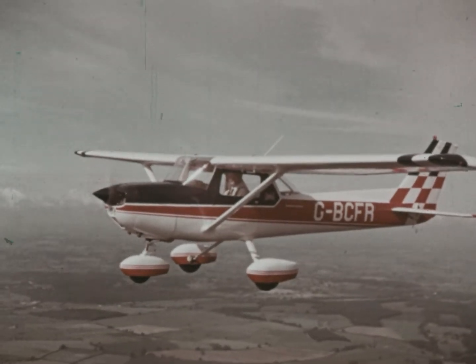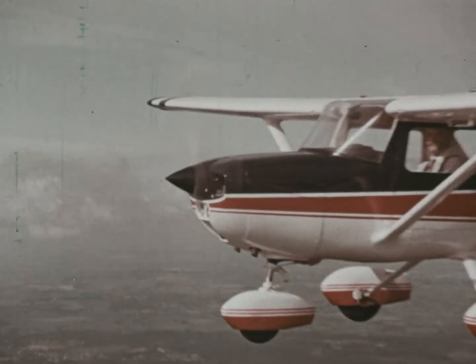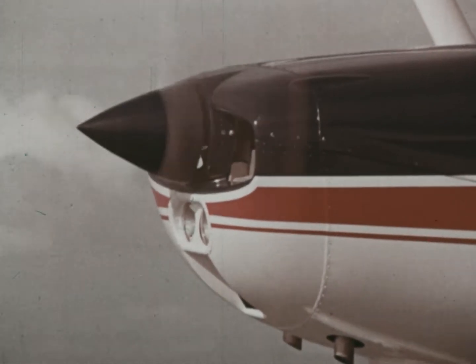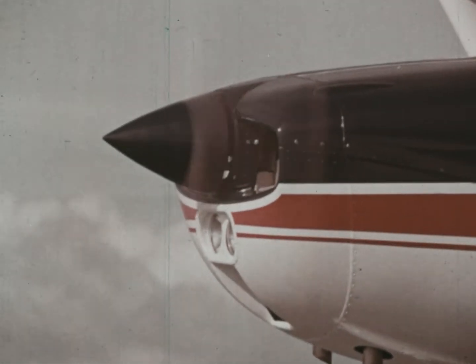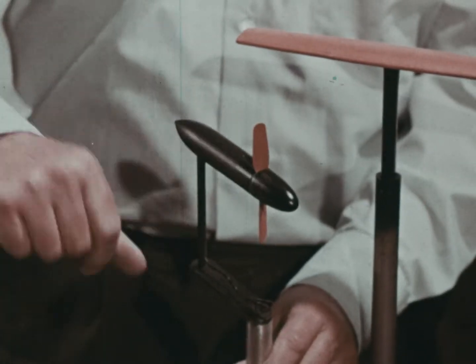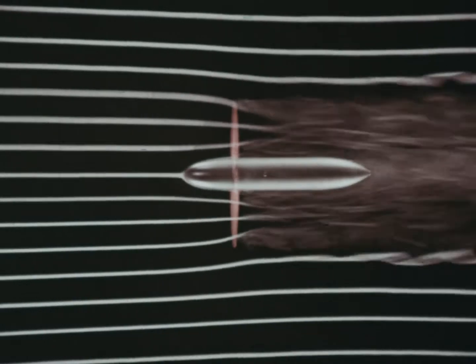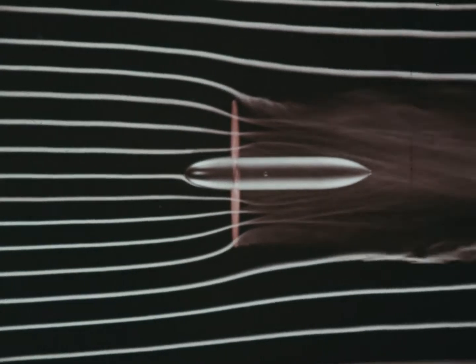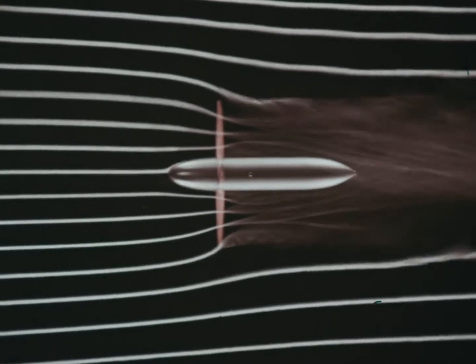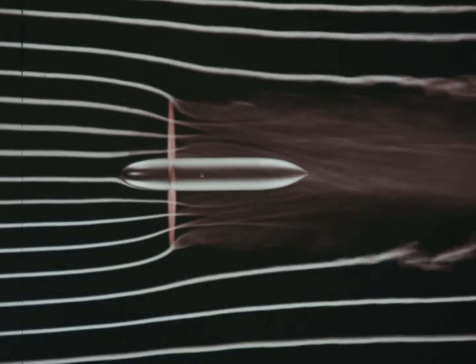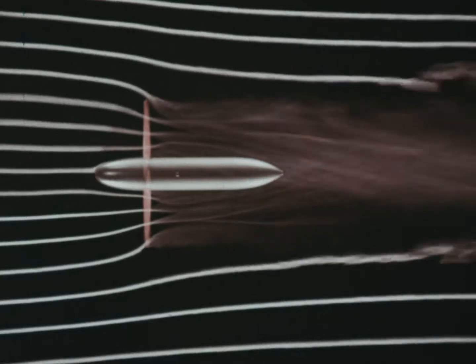To create and sustain thrust, the air must be accelerated by the propeller so that it moves faster than the airflow caused by the forward motion of the airplane. We can see this in the smoke tunnel with an electrically driven propeller. At rest, the air flows round it. Switch it on, and the air in front of the propeller is drawn in towards the blades and then accelerated backward at a speed greater than the forward motion of the airplane. It sets up a twisting wash in its wake, just like the propeller of a boat, only a lot faster.